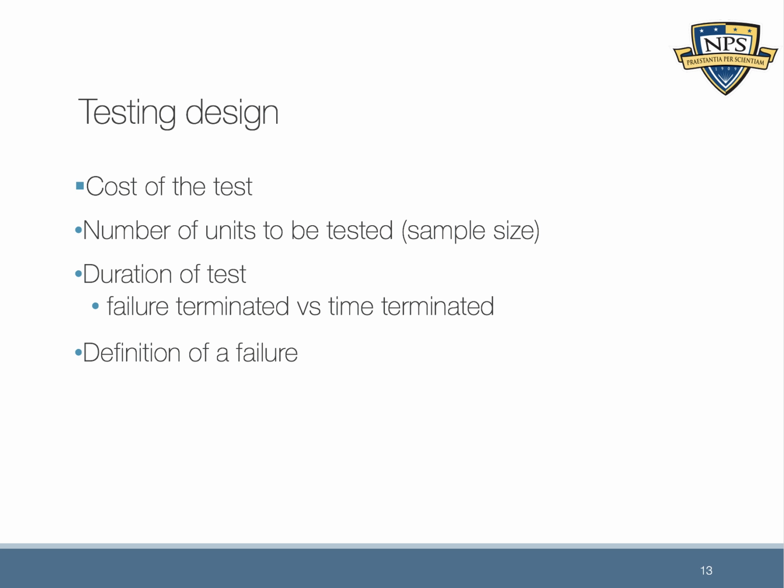But unless you say that we're going to use BIT, and the only output we care about is bit 100, which is the voltage, then there's an easy argument to say that if BIT fails, the test has failed, and it has to go through an FRB process before you can go back and retest it. So it's a simple example of the baggage that comes along with your test, because BIT tests a lot of things, and unless you really think about it, you're going to end up in a scenario where you can't continue your test to get your results until you go through a month-long FRACAS or FRB process.